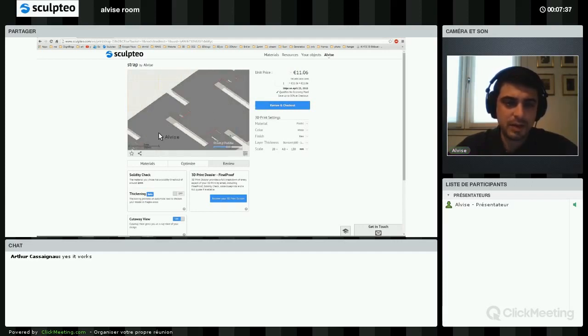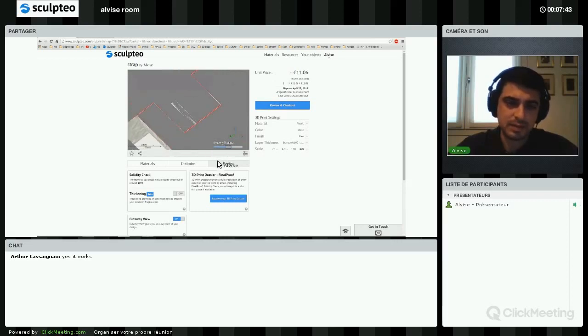So we can clearly see that the two parts are separated. I mean, all of the parts, 11 parts, are separated from each other. These red lines are the separation line, and there is some space, at least in a part here, that corresponds to 0.1 millimeters, and almost no space on this other side. So this is clearly not the right configuration we want to create an interlocked part.